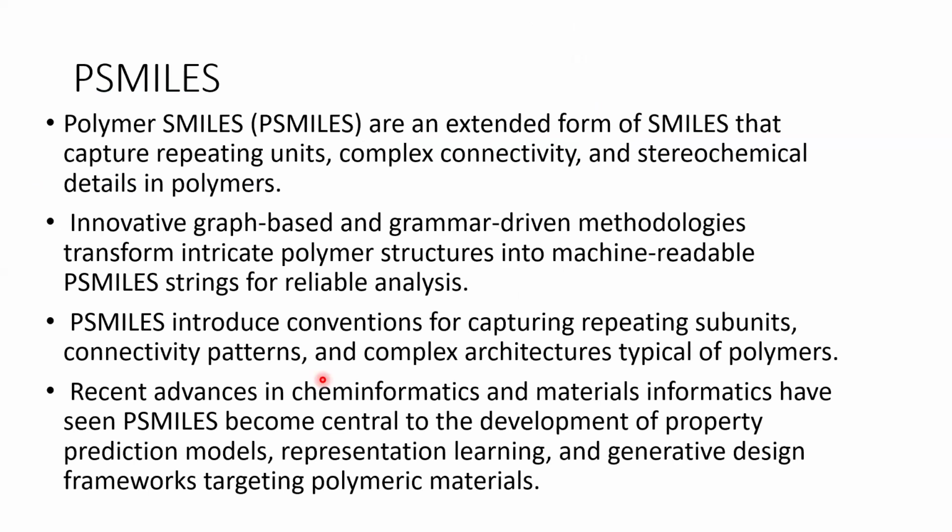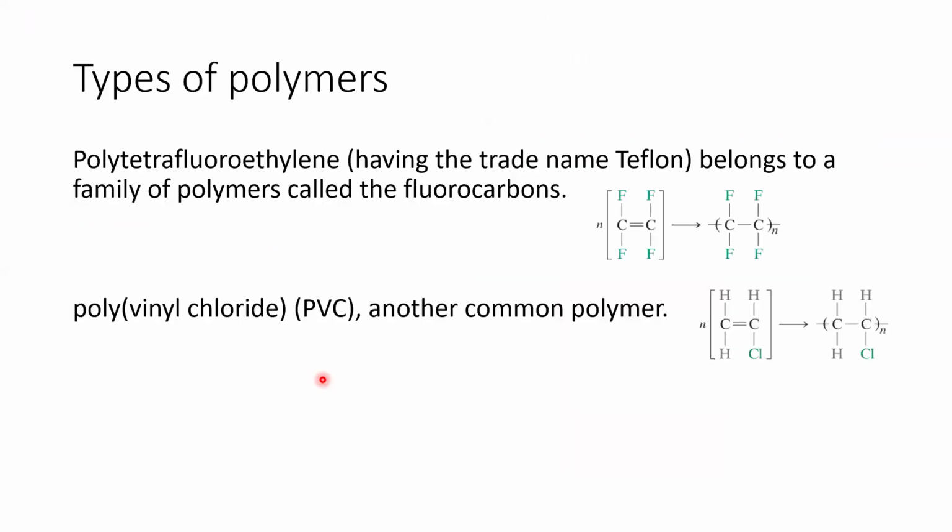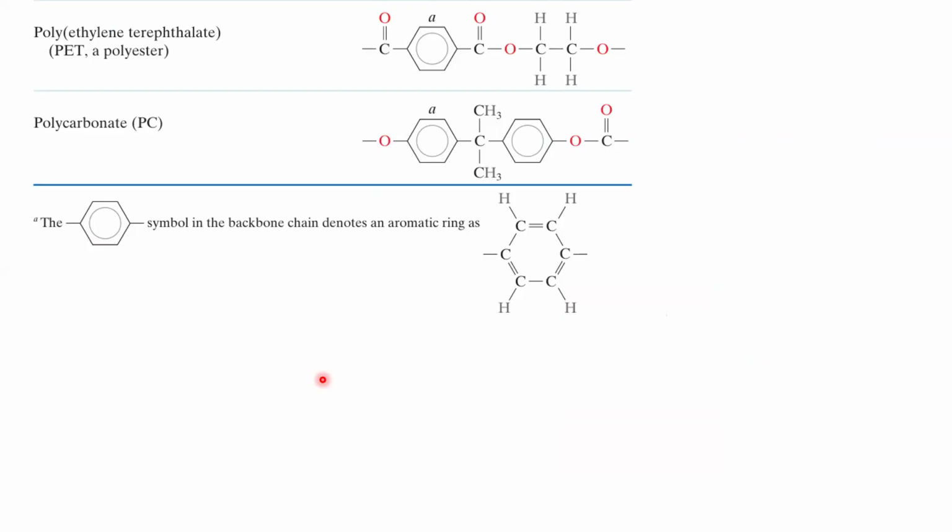So here, now we come to something. Till this slide, I have talked about the introduction of polymers and different types of manufacturing. Of course, I'll just touch on the different types of processing of polymers, which is very important. You have something called an extruder, where high performance composites and high performance polymers can be extruded. Extrusion methods are there, injection moldings are there, compression moldings are there, where you apply high temperature and high pressure, and you get a material. In the case of elastomers, you'll be using an internal mixer and a compression molding, and you'll get the molded material as your elastomer rubber composite, right?